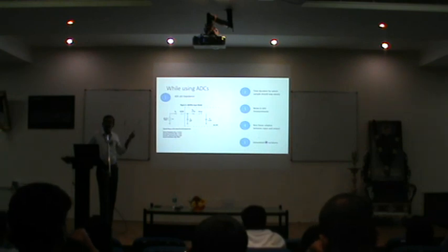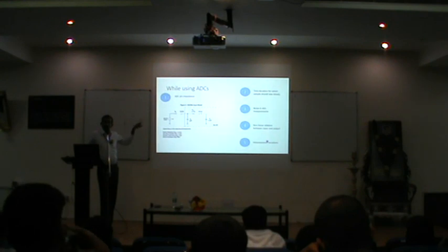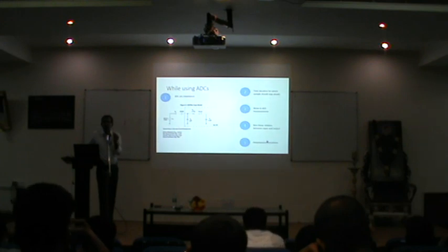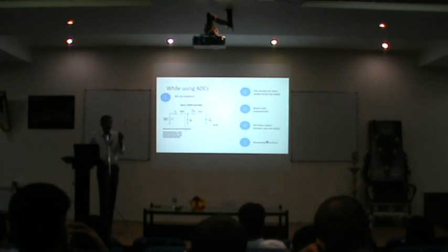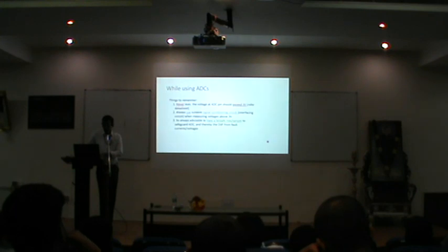If you feed the signal directly to your PI block, that feedback path, obviously you will have a stability issue. So the best thing to do is to average this over a period of time, maybe 100 milliseconds or 500 milliseconds, and average this particular speed value. Then feed it to your control loop, and you will have pretty good stability there. So that is about your ADC.